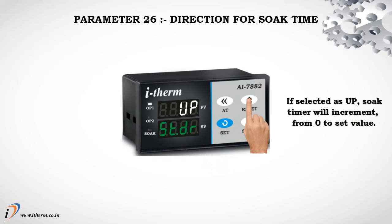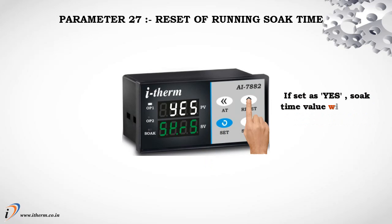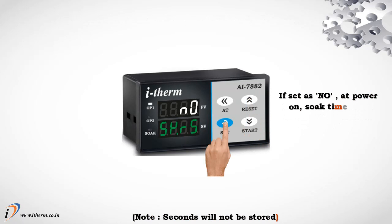If selected as up, soak timer will increment from 0 to set value. If selected down, soak timer will decrement from set value to 0. Parameter 27, reset of running soak time. If set as yes, soak time value will not be stored at the time of power failure. If set as no, at power on, soak time will continue from stored value.